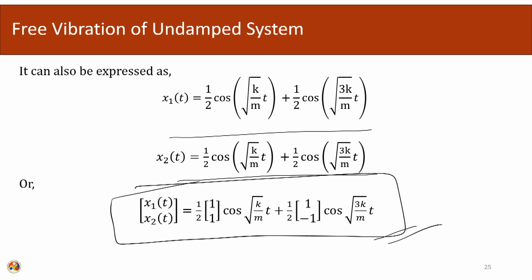We have evaluated the frequencies, we evaluated the mode shapes, we checked the mode shapes with the conventional knowledge that we have, and it agrees with the conventional shape. We can extend this same problem to a 3 degree of freedom system and check for the higher modes also, and subsequently increase the number of degrees of freedom.